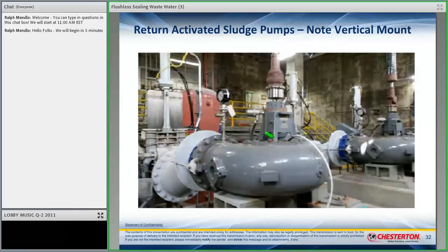If we had set this up with a flush with a check valve and a pressure regulator, the flush would be going all the time in the pumps, and that would be unacceptable as well. It would be good for the seal. It would allow the pumps to start easier, but they use a lot of water. Very expensive. So the solenoid approach in this particular case would solve this problem. The other approach would be a dual seal. That would definitely work, but again, very expensive.